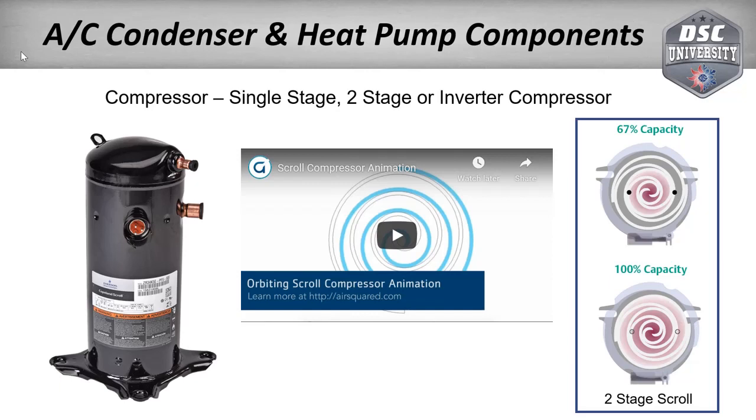What controls that? The thermostat ultimately controls it. On a two-stage thermostat, when first stage calls, it would turn the unit on at this rate. Some thermostats are set up differently, so I'll go with the most common. Let's say you've got your thermostat set at 75 degrees. As soon as it gets above 75 degrees, that thermostat's going to call. It's going to turn that unit on in first stage. If first stage satisfies the thermostat, okay, it's going to cut it back off.